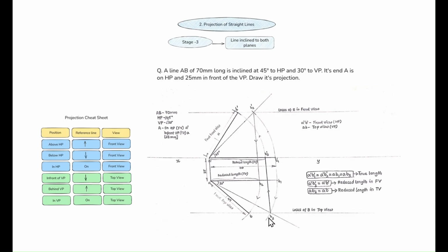You have drawn this A and B1, that is the true length, right? From that A to B1, take the compass and make the arc on that 30-degree angle line. Okay, you have made this. So you have made the arcs in the top view and also the front view, which is nothing but HP and VP. Done. Now what?